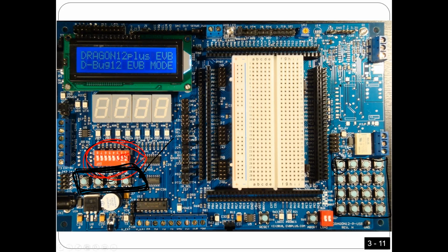You can see here, guys, it's written, this is number 1, this is number 2, number 3, this is A, right? It's like a keypad. So if I press here, I have to receive number 1. Let me say it in a better way: I have to receive the ASCII of 1, which is 31. That's what we're going to do now in the program. So if you press this button, you are given the ASCII of 1. This is the ASCII of 2, the ASCII of 3, the ASCII of A.